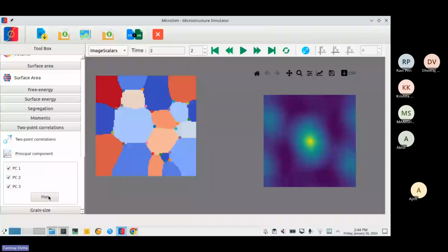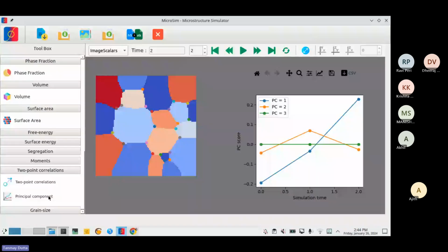So you want to take measures out of the microstructure, you can essentially compute what are known as principal components. These principal components, if you do the statistics like that, give what is known as the orthogonal base set. From that, you find out the particular variations in the microstructure which have the maximum value. The first three measures which have the maximum variation have this value.